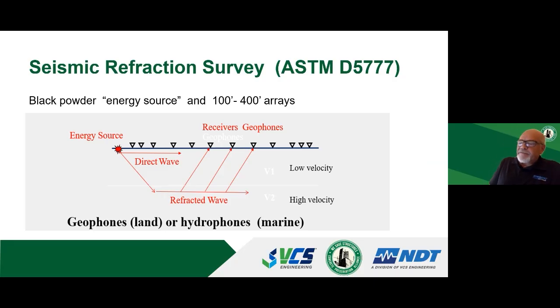Maybe they're spaced every 10 feet, and we can get a good indication on the general soil profile, but a continuous profile, not just a boring. A boring is a point location. It's just like a core in concrete. We're getting a profile all the way across our 300 or 400 foot line of geophones in the rays.